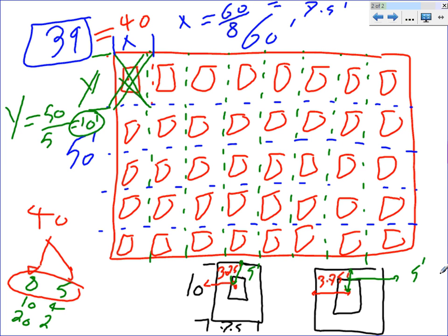You and the architects are working together, but ultimately, the architects have the final say. So if the architects did not design the grid, and it is different from what your calculation came up with, you have to follow the architects to the best of your ability. So you might have to shift these. This is not rocket science. You might have to shift them to match the existing grid.